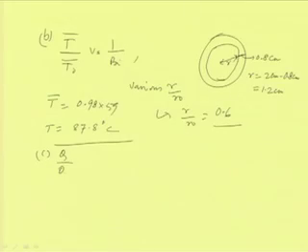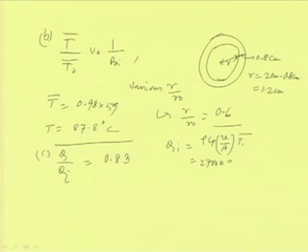Now, come to the part 3 of this, that Q by Qi. In this case this value is coming to be around 0.83 from the chart, and we know that Qi is to be found out equal to rho Cp into V by A into Ti bar, and this is equal to 2700 into Cp, something around 900, and the V by A is R0 by 3, and we know Ti bar.